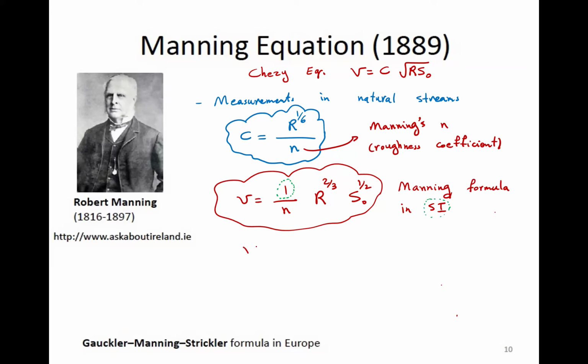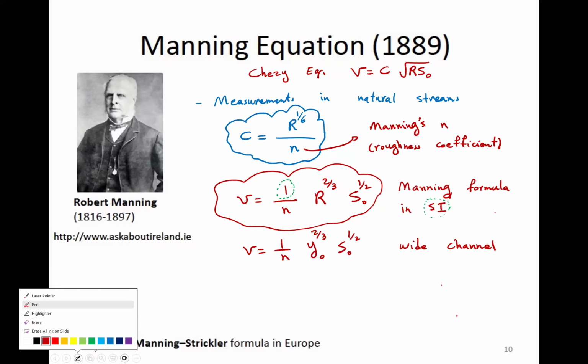Now, if we have a wide channel, nothing changes except depth replaces the hydraulic radius. So 2/3, S naught 1/2. So this would be for a wide channel. For natural streams, if they're wide, you can simply use this equation and get the resistance and velocity and depth.